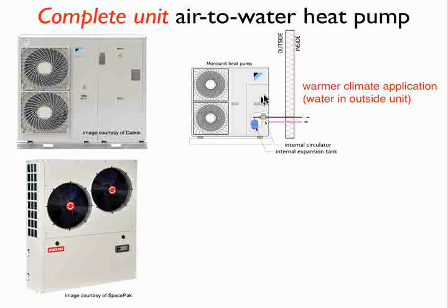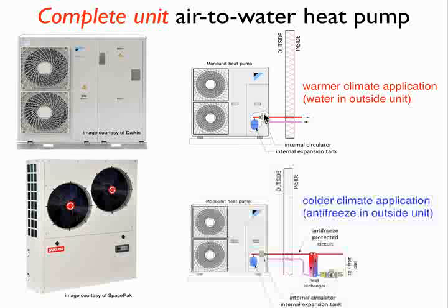For example, when the outdoor temperature drops below typically about 40 degrees Fahrenheit, they'll automatically turn on the circulator inside the heat pump and create circulation. Some of them also have an electric resistance heating element that will come on at a certain temperature. But ultimately, in a power failure, the only thing that can prevent it from freezing is antifreeze.